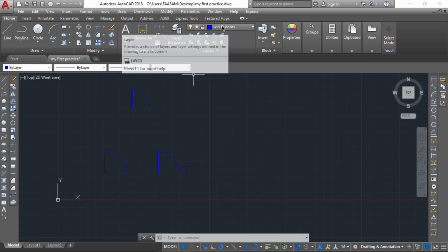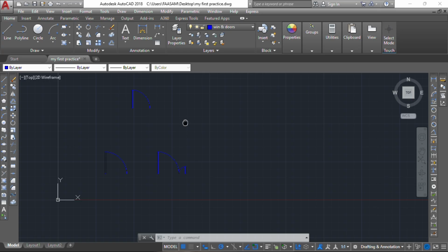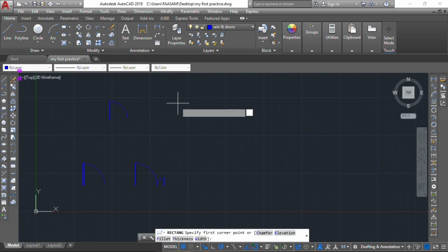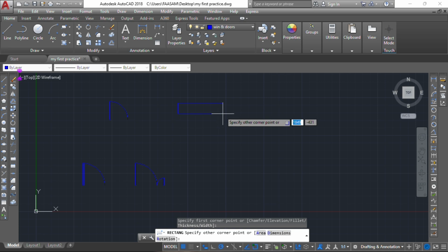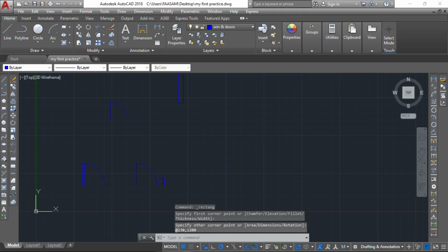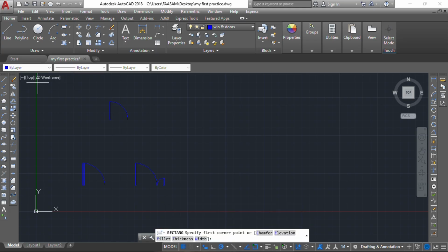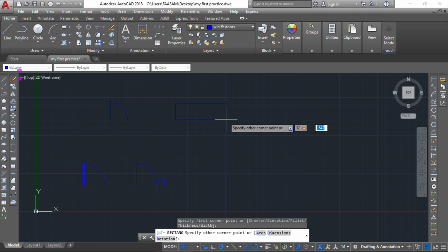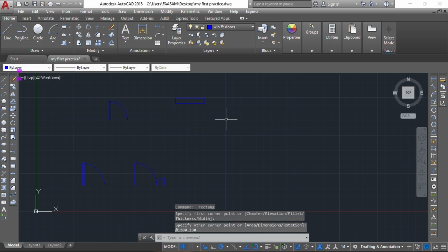Okay, our layer is still in windows and door for our 2D plan. So just the same method, let's click on this, and then let's expand it. Since we'll be using 230 for our walls, now let's put the thickness of our wall 230, comma, and our window width is 1 2, as said earlier. No, sorry, I think 1 2 should come first. 1 2, comma 230. Enter.